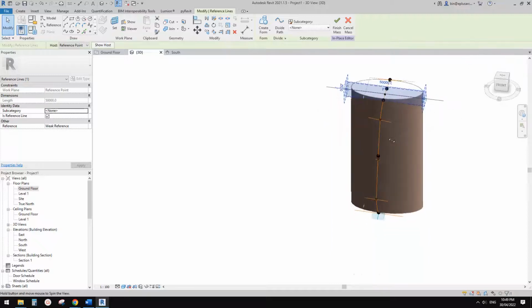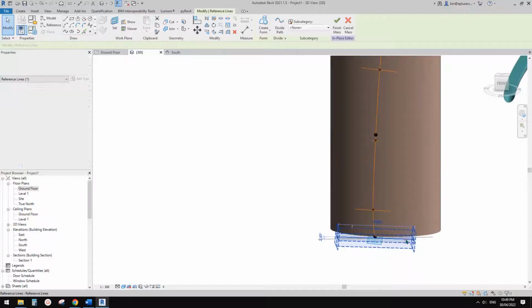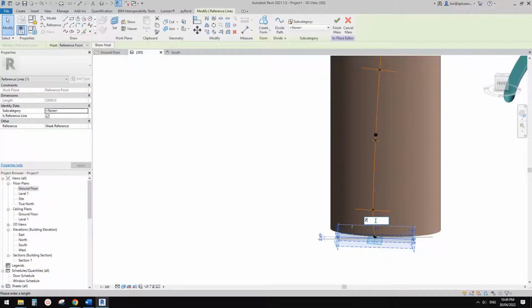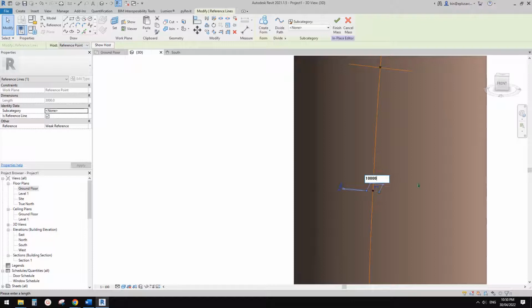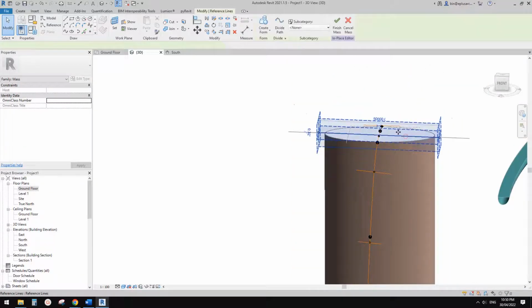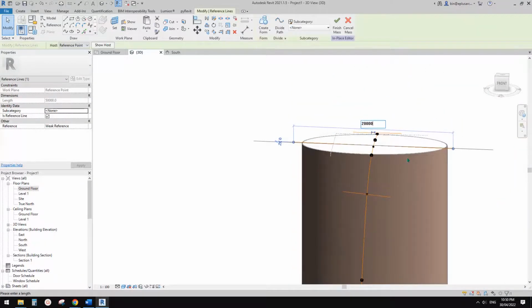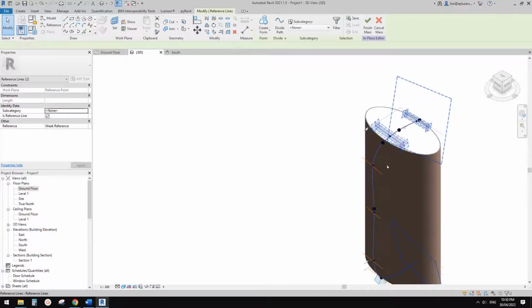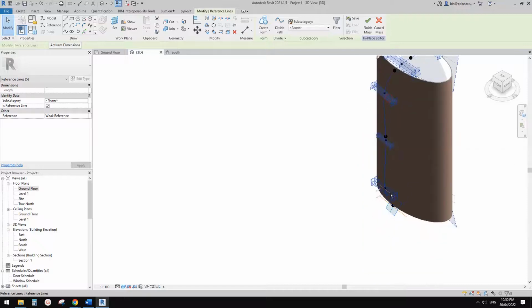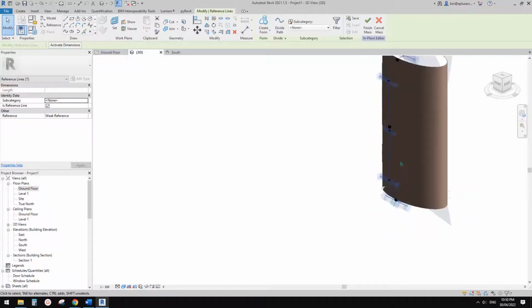If this happens, try to make all these profiles similar size first. Instead of very big differences, try to reduce the difference between them, create the shape first and then adjust them. So let's try it again.